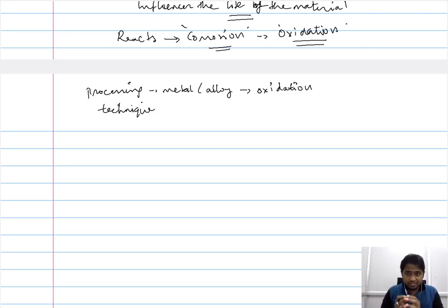So that is the weight of oxidation in the realm of processing techniques, and that is one additional reason why, when we consider the high temperature behavior of the material, we also need to consider high temperature corrosion, particularly high temperature oxidation. Now the reason why we need to consider high temperature oxidation is because oxidation occurs when the metal is exposed to air. So we don't have to have a specific environment for this corrosion to take place. Rather, this form of corrosion generally happens when you expose the material to air, and that is the reason why we focus on this particular mode of corrosion.